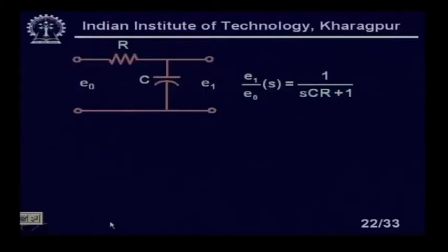Now, again we are coming back to our RC circuits, which are used for simple dynamic measurements. In that case, the carrier frequency should be much higher. That means the excitation frequency should be at least 10 times higher than the maximum expected dynamic signal in the LVDT, right. What is the dynamic signal here? The dynamic signal is the movement of the core, which is the input. So the frequency of the dynamic input component should be 10 times lower than the frequency of the excitation of the LVDT, clear.